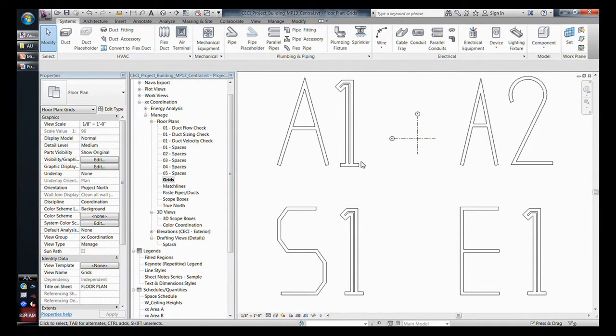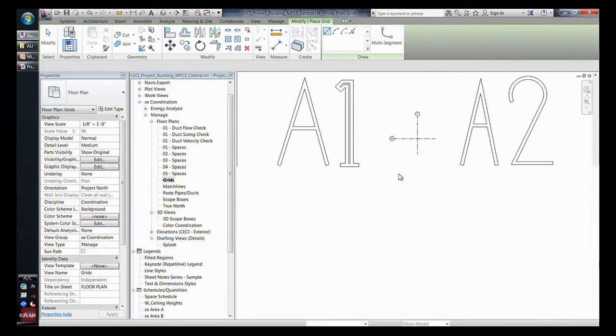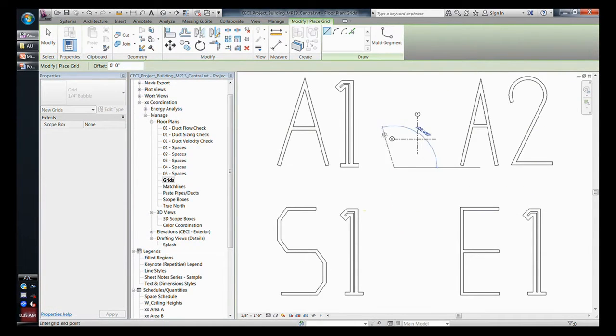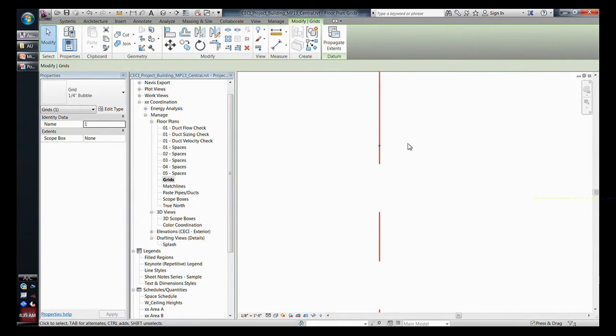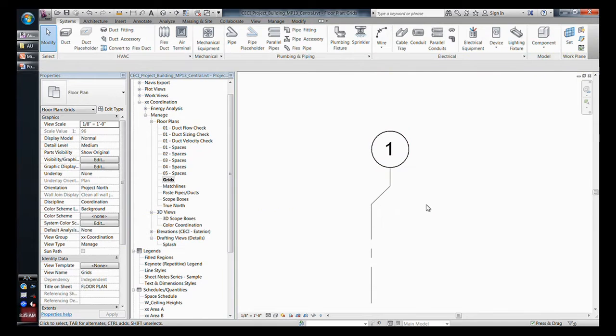I know that's not always possible. If the architect has grids that are too close to each other, they're going to break the bubbles apart by what I call little z, right? You guys know what I'm talking about? I already have a couple of grids here. So whenever the architect is using this little z, and they break it like this, it is a 2D change considered by Revit. And what that means is it's a change only for this view.